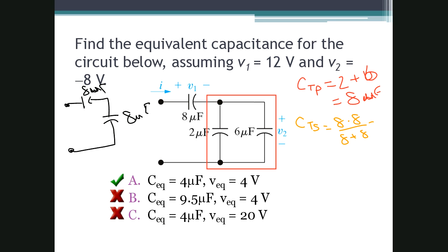And I can tell you right now, when you have the same value, and you're doing resistors in parallel, inductors in parallel, or these series capacitors that are the same value, there's a quick shortcut: if you know they're both the same value, it can't be any higher than half of that value. So in this case, since they're equal, it's actually going to be 4 microfarads.